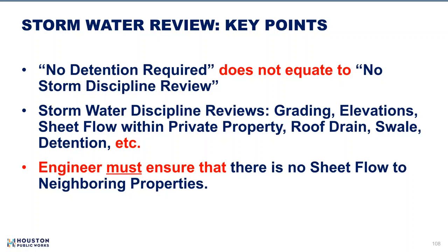I want to share with all of you, and I've been telling a lot of people over and over again, so I think it's best if I share it with this audience: when we say no detention is required, some of you can probably recite it, less than 15,000 square feet, less than 65%, then no detention is required. But no detention is required does not equal no storm drainage review is required.